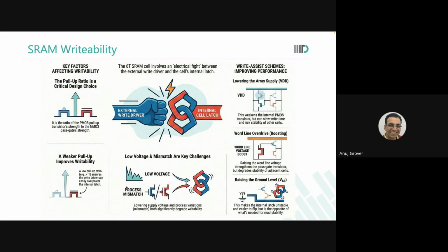All currents that are going to flow in any system, any device, are in some way dependent on VGS minus VT. Now, what is VGS? VGS has some semblance of VDD in it. Right? The gate has VDD, the source has 0, so VGS is mostly about VDD. I would not say exactly VDD, but a semblance of VDD in it. And from this you are reducing VT. That is what is going to define your current. So if you increase the VT, it is as good or bad as lowering VDD by that much voltage.